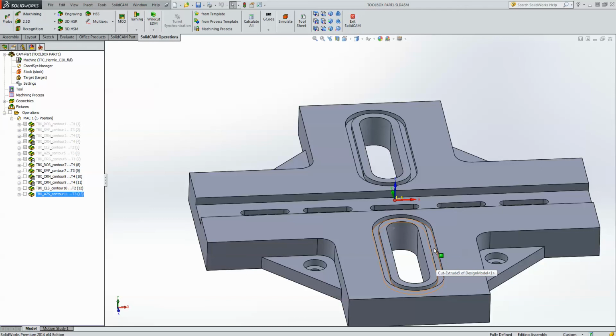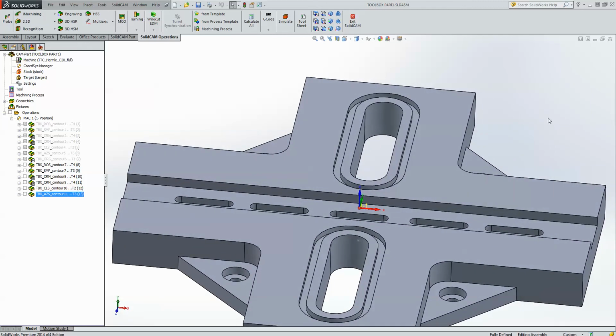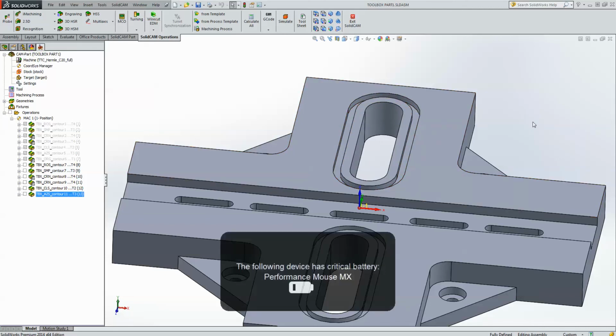Now, these are actually evenly spaced walls between each other, which are used for O-rings. So we have a specific operation called O-rings. Now, the way I like to work at least, is that I would go into here with a smaller end mill. Let's say the width between this edge and this edge over here is a total of 4 millimeters. So I'd like to go in there with a smaller end mill, say a 2 millimeter end mill, go down the exact middle of that slot in a helical fashion, and then once I'm finished the middle, then I'd like to go off and clean one side and then the other side as well.